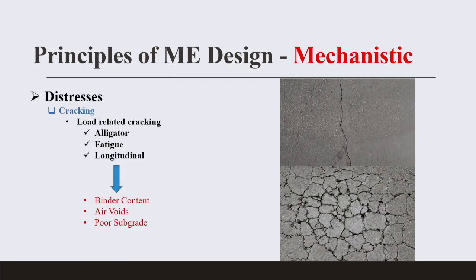So here we are still talking about distresses. We know what distress is, and all these things are predicted, shown within the system. So they've actually developed distress functions or transfer functions within the MEPDG, which you can use. Or if you have developed a lot of data, you can even go in and modify those equations to meet your specific country requirements.